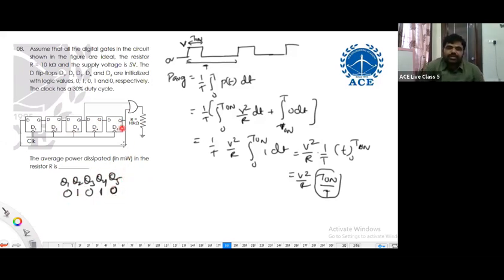What is the next state of this? Which counter is this? Ring counter, 5-bit ring counter. Check it. It is a 5-bit ring counter. What is applied here as D input? Output of the last flip flop. It is a register, a 5-bit register. Output of the last flip flop is applied as input to the first flip flop.